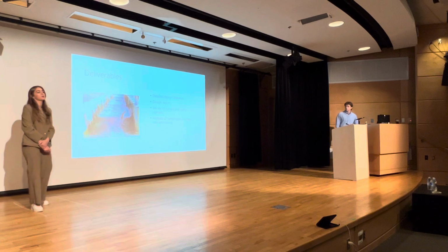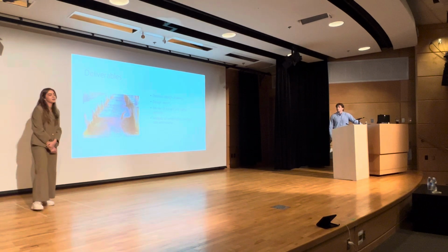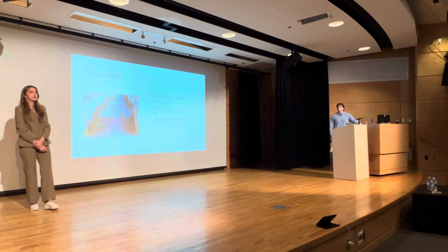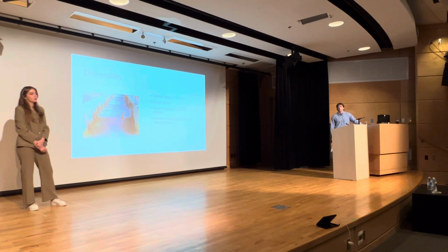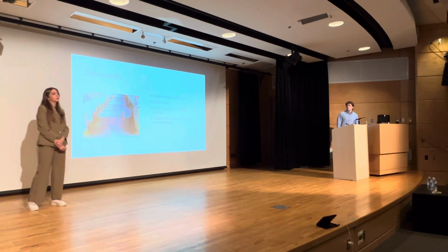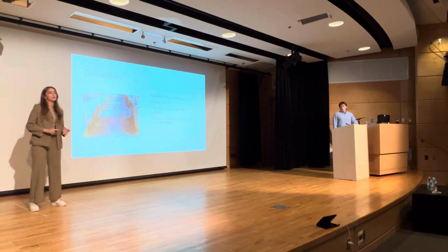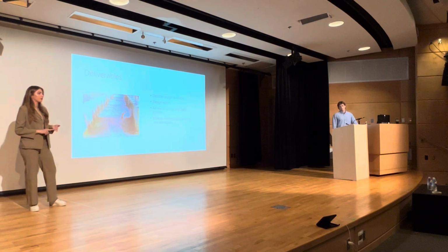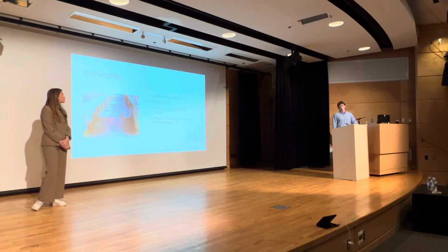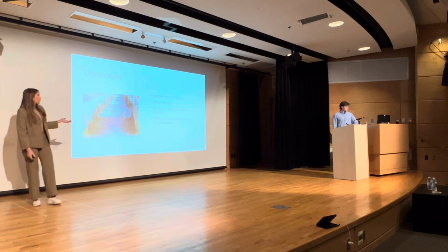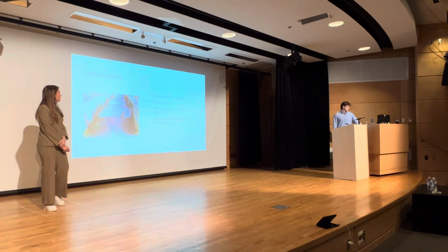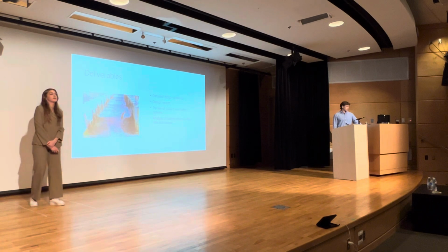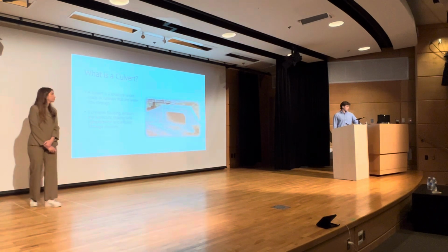Our deliverables. We will be delivering detailed design drawings, which will include our existing and our proposed culverts, and also our road cross sections. A design report, which will include our flow calculations, our culvert sizing and type, and our fish baffle sizing and type, and the reason why we chose them. Again, a review of the culvert and baffle options and the calculations that made us choose them, and the analysis of the rainfall data and flow checks for the watershed.